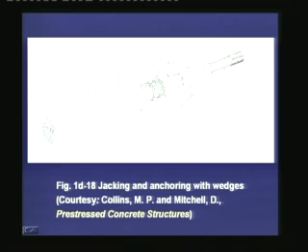and wedges. And here we can see that once the piston moves in one direction, the tension is applied. Now once the tension is applied, then the piston on the other side moves back the other anchorage block and places it against the bearing plate, and the wedges are appropriately seated in the anchorage block, and then this extra amount of the strands are cut.